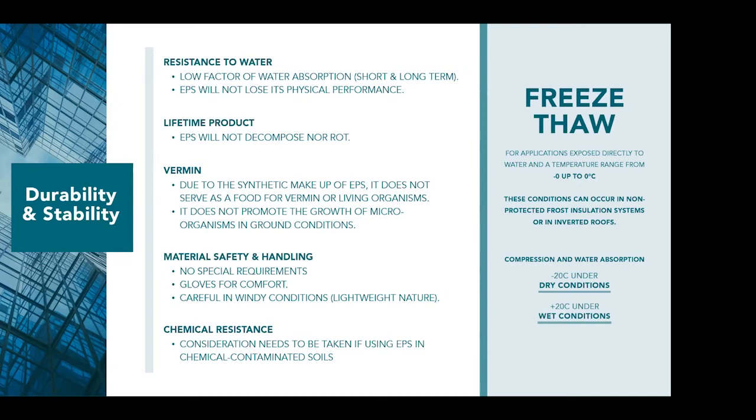Freeze thaw. Again, something just to be aware of. Determination of freeze thaw resistance is only needed for applications where EPS is permanently exposed directly to water, with a temperature range below 0. These conditions can occur in non-protected frost insulation systems, where we have no gravel layers or insulation underground, or inverted roofs.